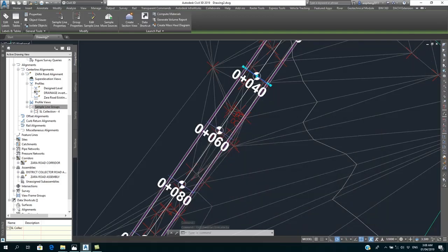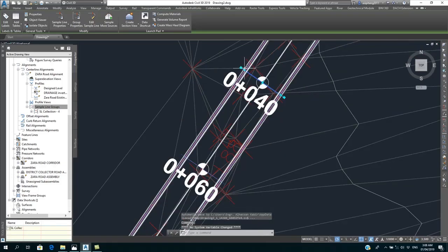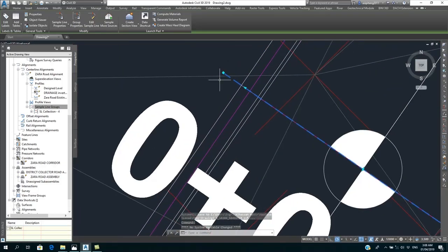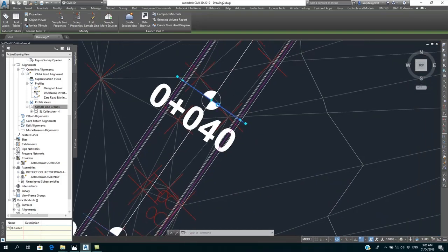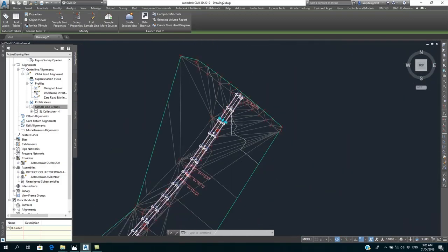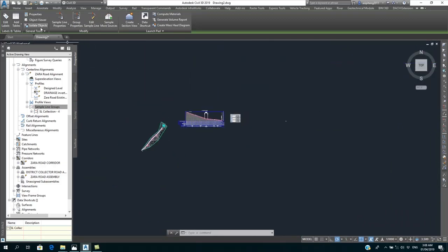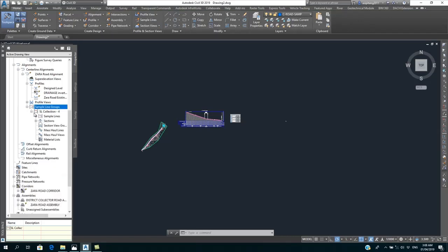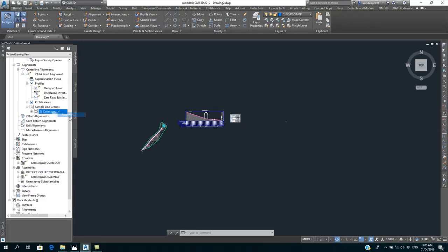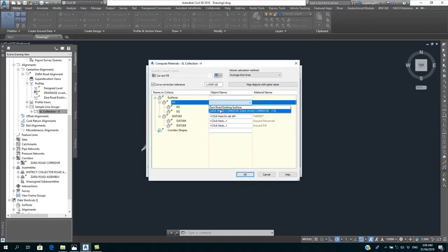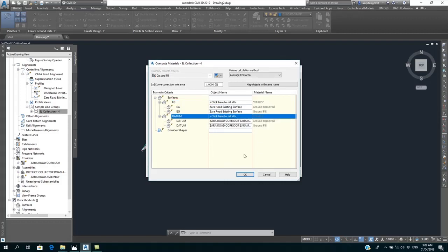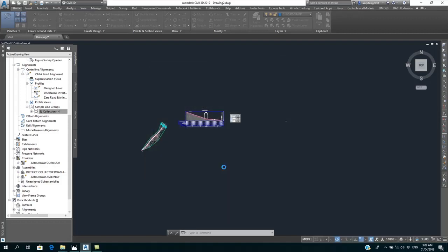You can see, so these are side line offsets. It covers the extent of the corridor. You can see you have some offset to define the existing so that the line will come back to the existing structures. So I have my corridor sample line defined. After you define your sample lines, the next thing is to come to that sample line collection, define the properties under alignment, select the criteria of functions for cut and fill, then existing ground is the surface, then the datum is the corridor. Then you click on it to get the details. So from here now, I can get my volume analysis report directly.